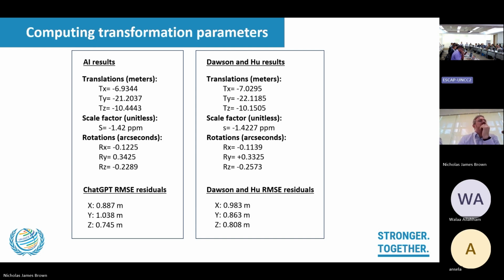Just to let you know, Nick, with these transformation parameters, we have compared the observed coordinates and converted coordinates and found these residuals all around the nation, where we had to observe on islands, because there are about 300 islands in the Fijian archipelago. So we did some GNSS observations and compared them against the converted ones as well. We found the residuals around a meter or so, or maximum 1.5 meters.